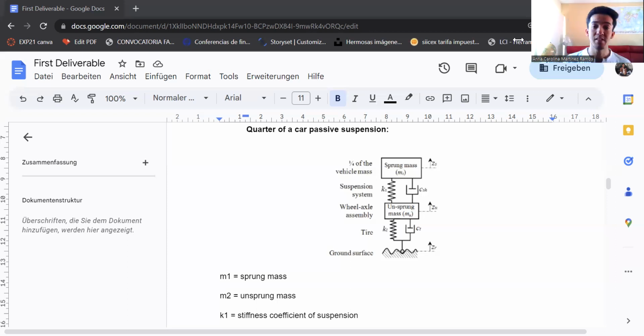In order to anticipate potential road defects, active suspensions regulate the vertical movement of the wheels and make use of numerous processors and sensors. The sensors continuously track how the anti-lock brake system, vehicle frame, and suspension are moving. The properties of the parts, springs, and dampers in the passive suspension system are fixed according to the design objectives and the intended use. The suspension designer chooses these qualities. A passive suspension has the ability to store energy via a spring and to dissipate it via a damper.